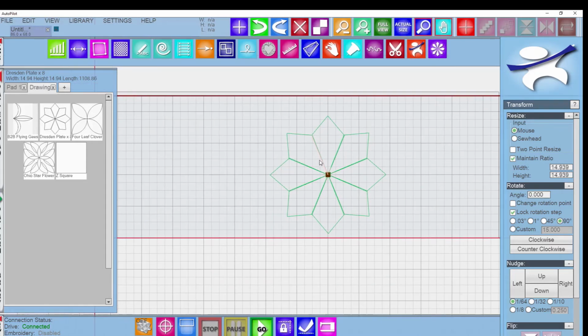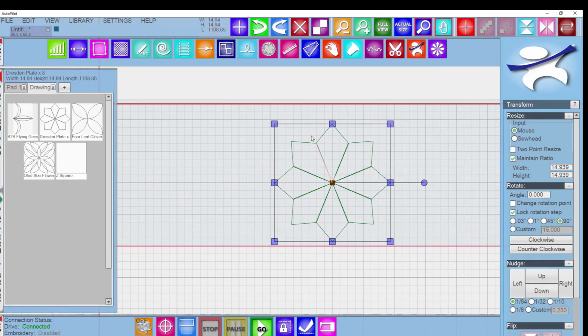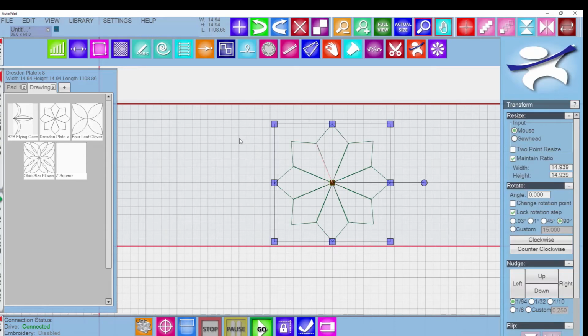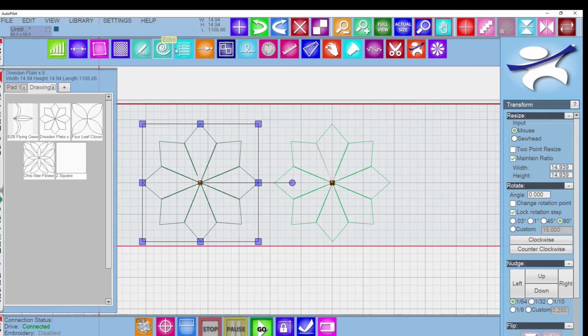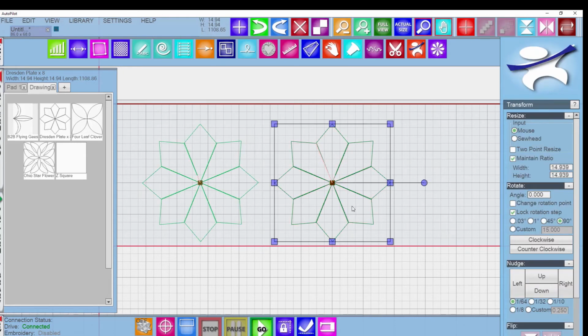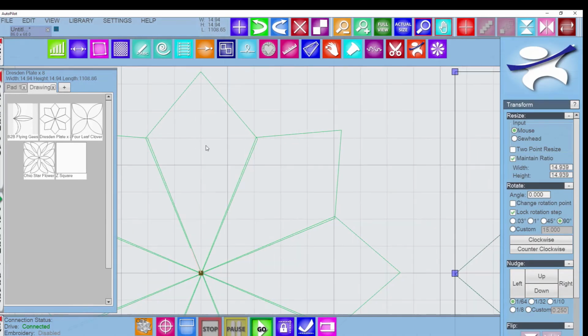Now there's a little bit of an issue where if I want to try to draw on this, when I go to the draw menu, it will reduce it down to just one shape, no matter what you do to group it or link it. So you can get around that. A workaround is to export that as a pattern, or to save it as a pattern, which I've done here. So now when I bring it in and take it into my draw menu, it stays intact. It doesn't really matter that you have all of it, but that's just, like I said, a trick to do it, a workaround. So let's go ahead and design a pattern.